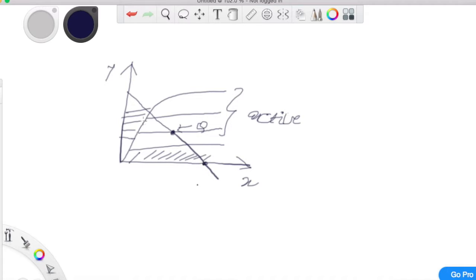If you put y to 0, you'll get the value of x. Similarly, when you put x to 0, you'll get the value of y. Hence, whatever values of x and y you get, you'll get the Q point. So this is how you form a DC load line.